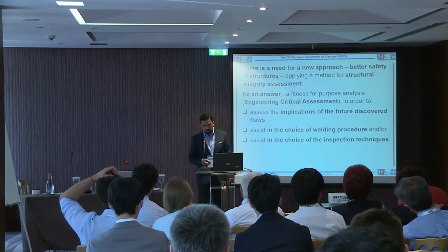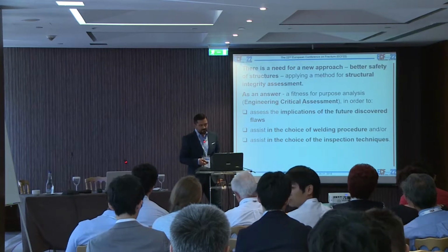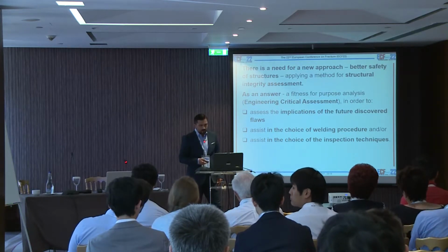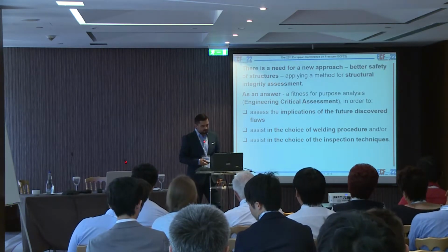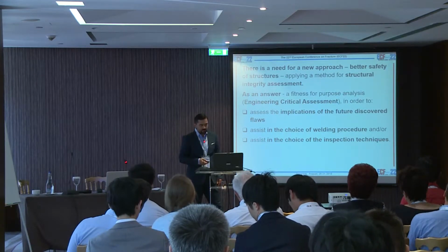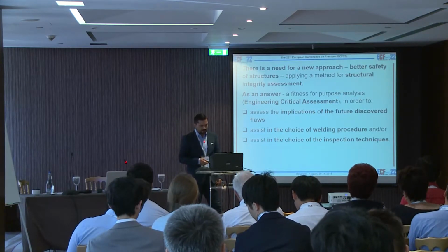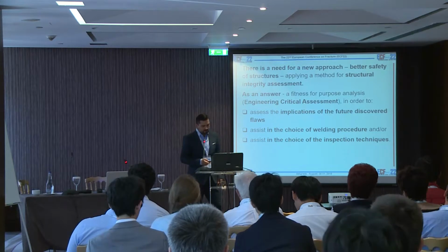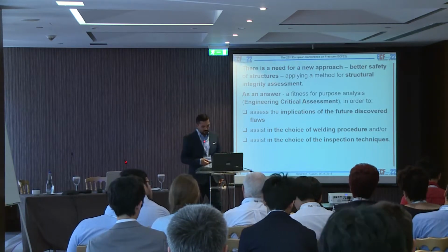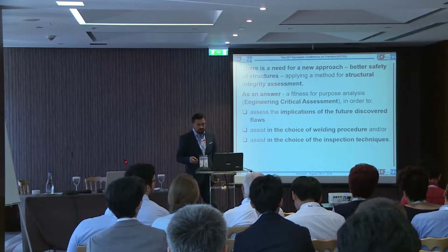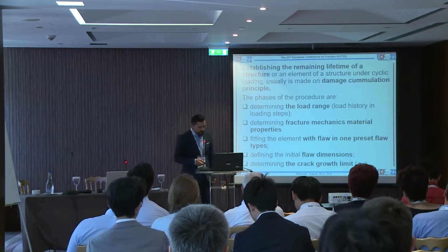As an answer can be the engineering critical assessment, which can be done to assess the implication of a possible flaw discovered in a structure, or to assist in the choice of the welding procedure, or to assist in the inspection techniques.